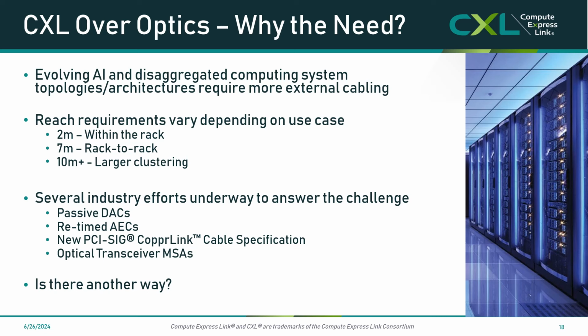PCI SIG sees the need for this. They've recently released the latest copper link cable specification, which really presents use cases for PCI Express cabling, PCI Express interconnect over twin-ax cable, using industry standard MCIO interconnect for inside the box, and then industry standard CDFP MSA solutions for outside the box that supports both PCI 5, PCI 6, or in the CXL world, CXL 2, CXL 3,